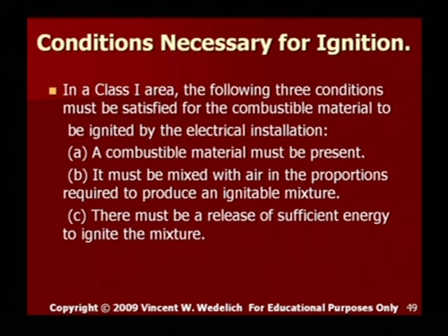And then there must be a sufficient release of energy to ignite the mixture. So that could be a heat source above its auto ignition temperature, or it could be arcing, a breaker opening or closing. Once the breaker opens, it arcs. And when it arcs, that's sufficient energy to ignite the mixture.